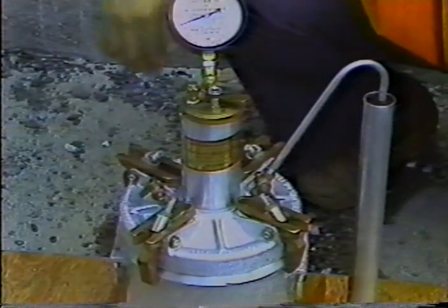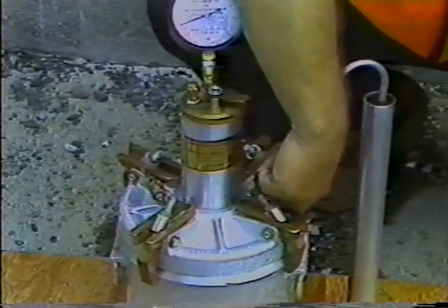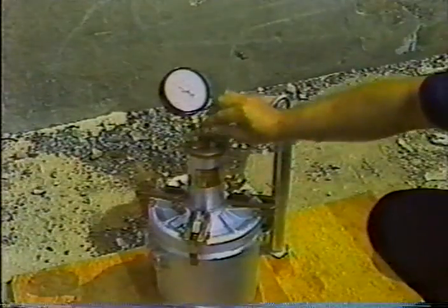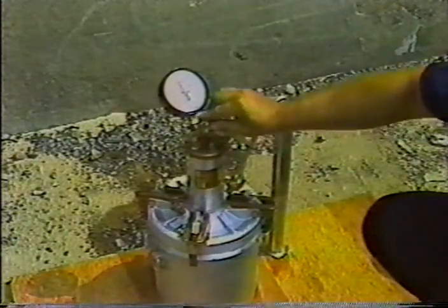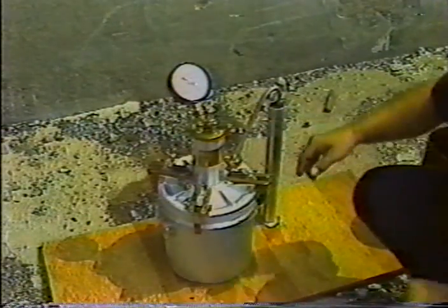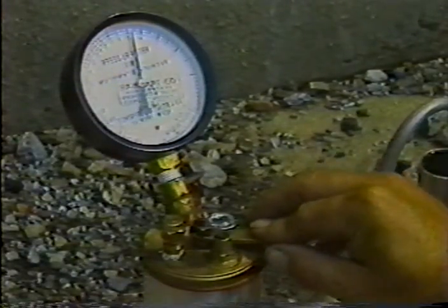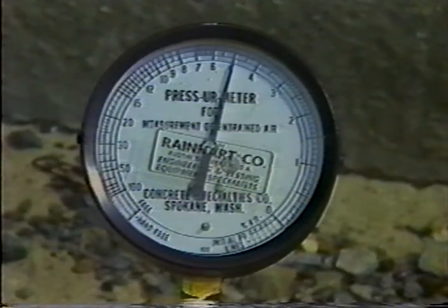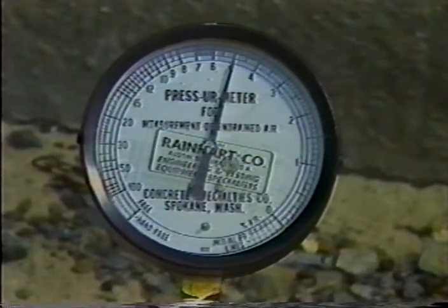Release the air at the free petcock. Open the other petcock and let the water in the curved tube run back into the base. There is now 5% air in the base, or whatever percentage is represented by the vessel. Next, with the petcocks open, repeat the steps of pumping to initial pressure line, stabilizing the dial hand, closing both petcocks, and immediately holding down the thumb lever, and waiting for the dial hand to stabilize. Read the percent of air on the dial. It should be 5%, or whatever percentage of volume is represented by the calibration cylinder.